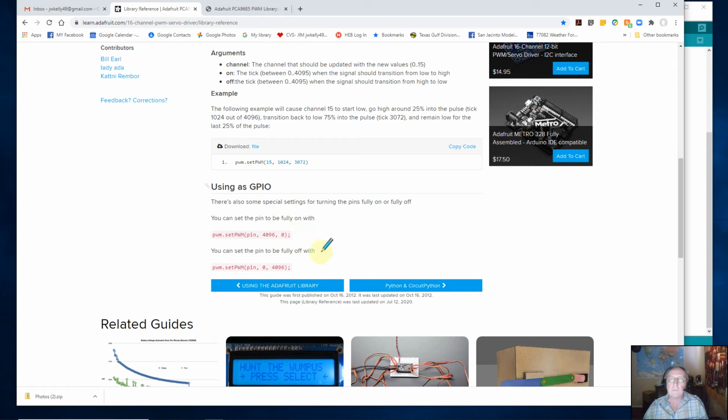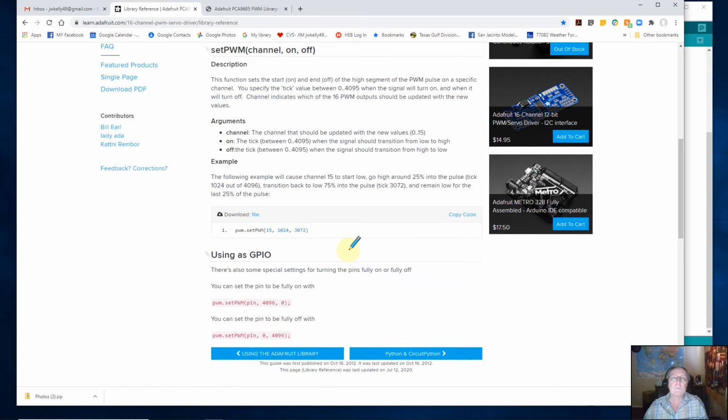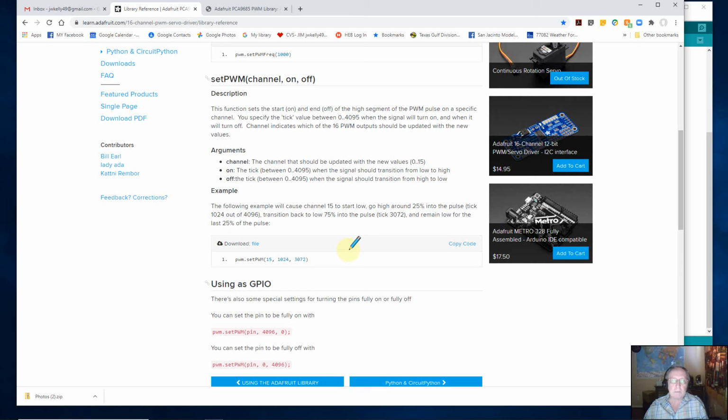Now if I want to turn it off, I would go back to that same pin number, but I would reverse those numbers. I would set the 0 and I would send a 4096, and it would turn off and stay off. Does that make sense? I hope that brightens your day up a little bit.